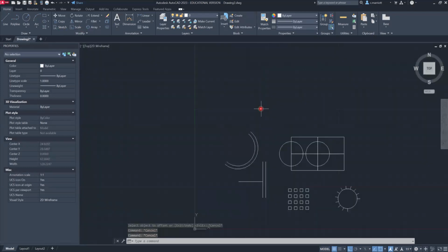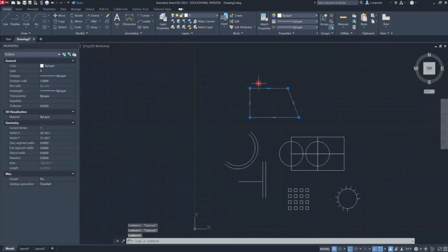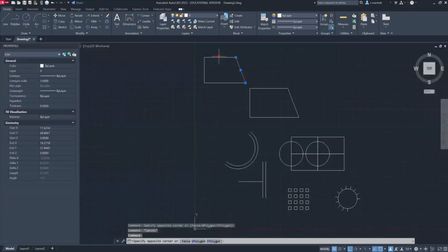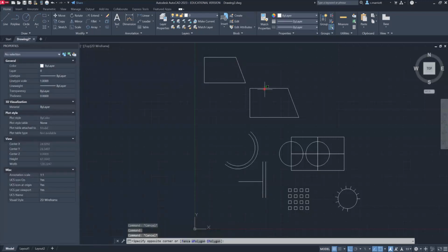Okay, let's do the stretch tool. So let's say I have an object drawn that looks like this. Okay. Now, I just made this using something called a polyline tool. I typed in PL to do this. And the difference between a polyline and just a series of lines is that this is joined into one object. If I had used the line command to make this, you'll see that they're each individual items. If you use polyline, it's going to join them into one.